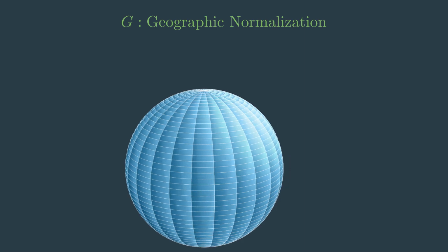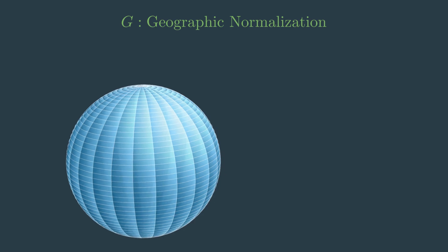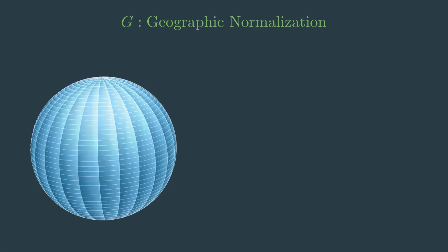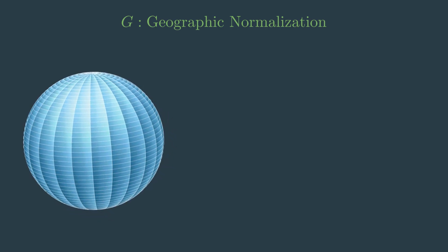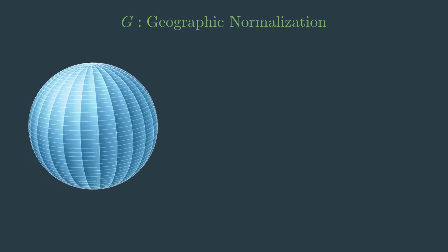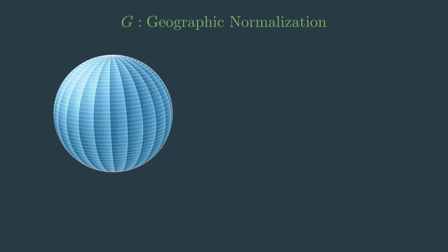So now we have these two sets of coordinates, one for each side of the street, rotated, mirrored, but they're still in meters in this temporary flat world. Correct. Still in the ENU playground. How do we get them out of the playground and onto the real curved Earth map with actual latitude and longitude? That's the crucial translation step back to reality.